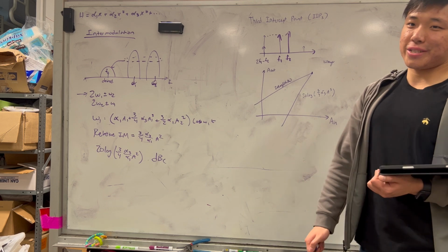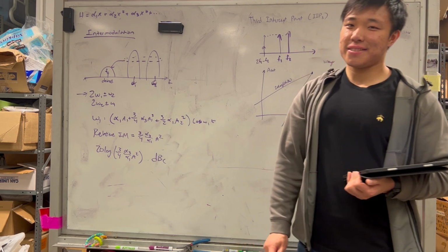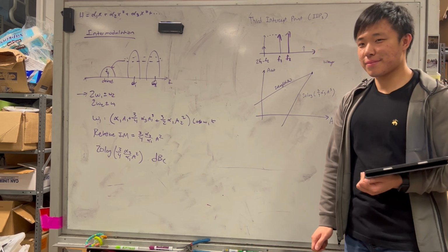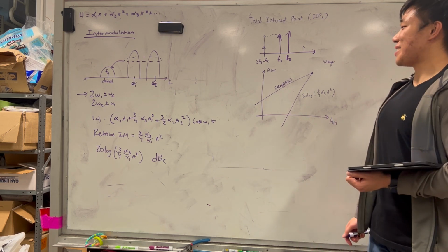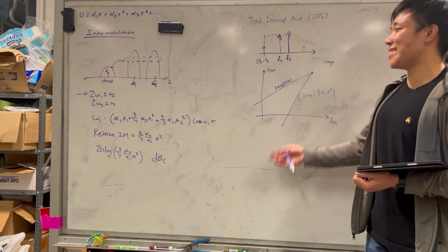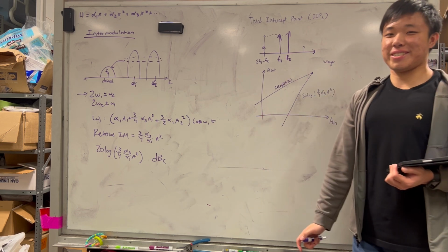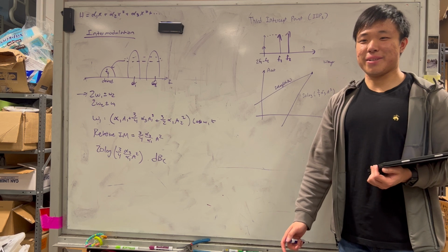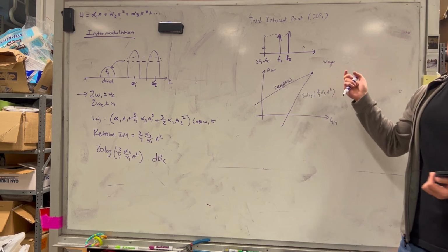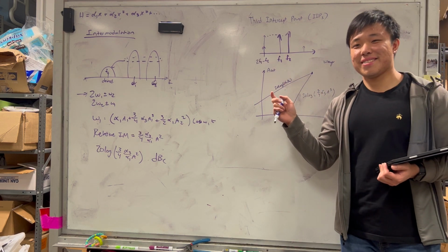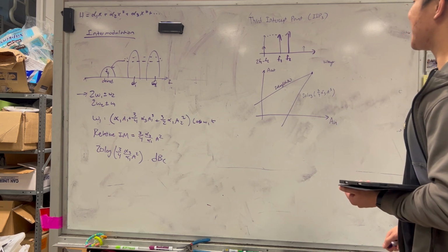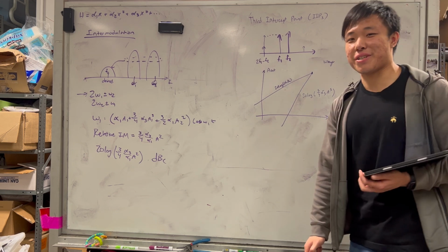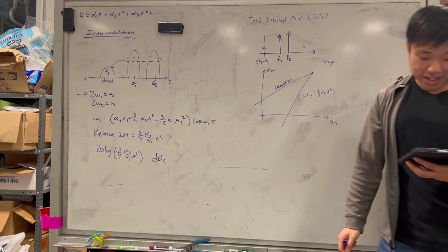Which one occurs first? What do you guys think? It's a really simple vote, I guess. Who thinks compression point happens first? Okay. Who thinks the IIP3 happens first? Very nice. So it turns out that the compression point will actually occur first rather than the IIP3 point.